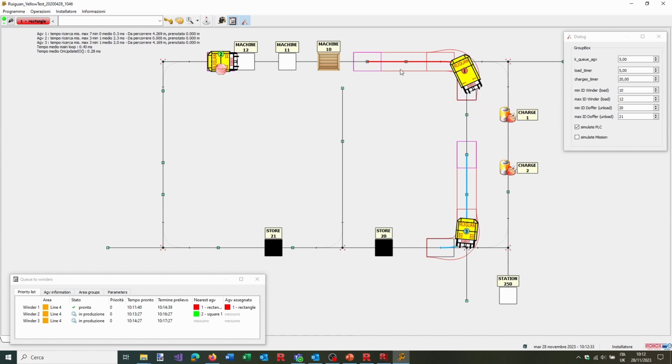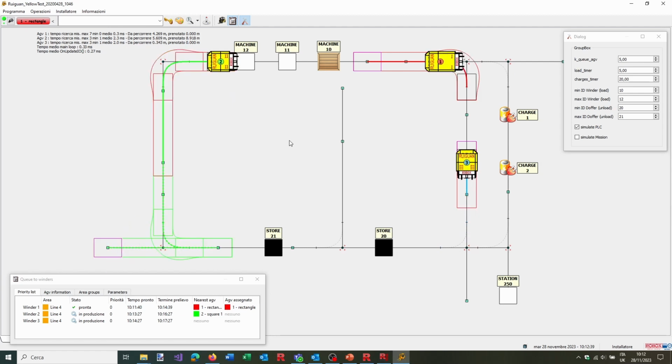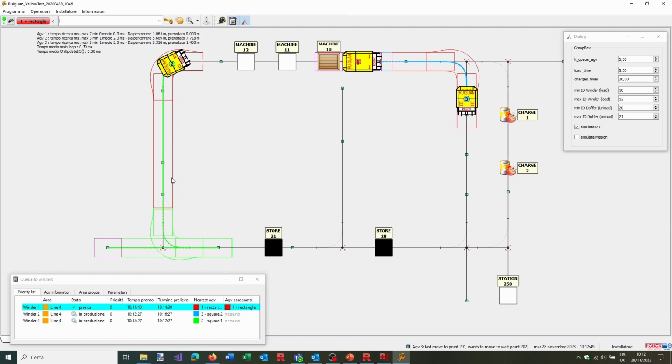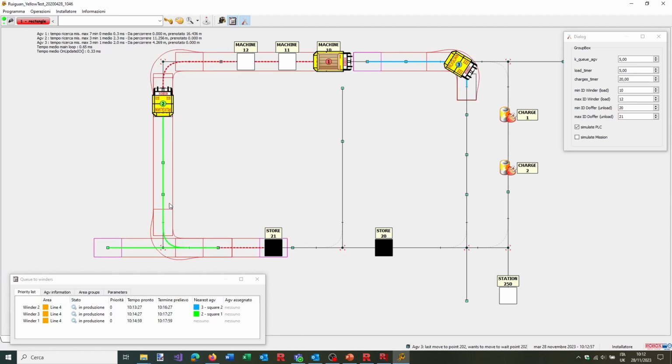Of course, reserved means that no other AGV will be allowed to touch this line. There will be no cross and no other AGV can come here. Only this AGV will come, and the others will just remain in the requested part. More requested areas may be overlapped by more AGVs, but only one can reserve it at a single time. Now, you can see, for example, the red and green are requesting the same path, but only green can